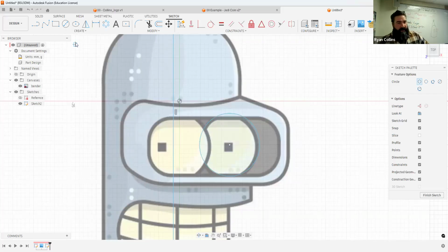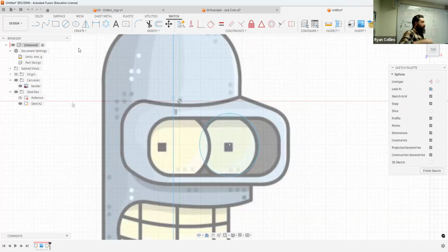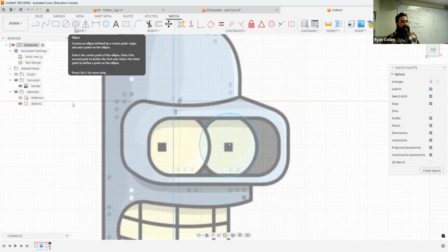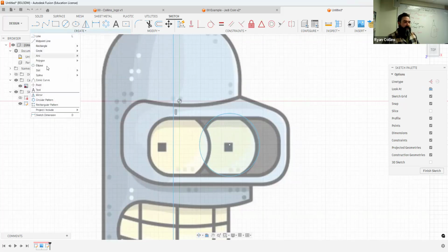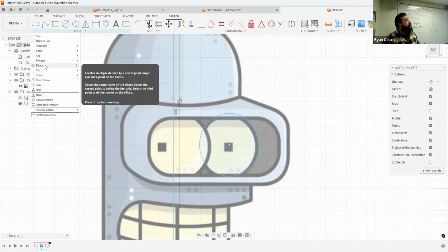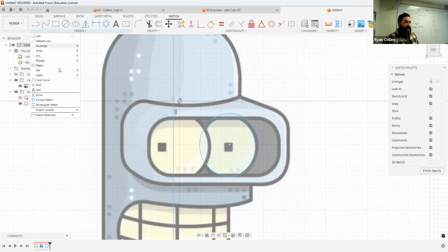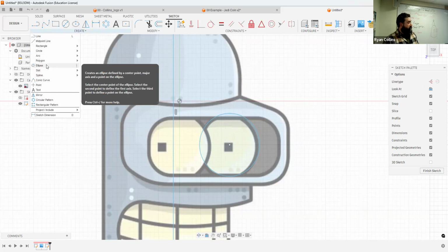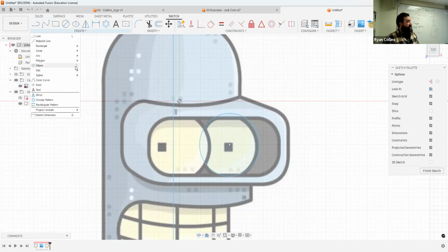But one of the other questions was, all right, you got that, but I want to make it an oval. That is a separate tool called the ellipse tool. If it's not already on your toolbar, you can add it, but down to create, and you just go to ellipse. You can alter what is available up here on your toolbar. As I mouse over this tool, the ellipse tool, an ellipses symbol shows up. That's those little 3 points next to the thingy.